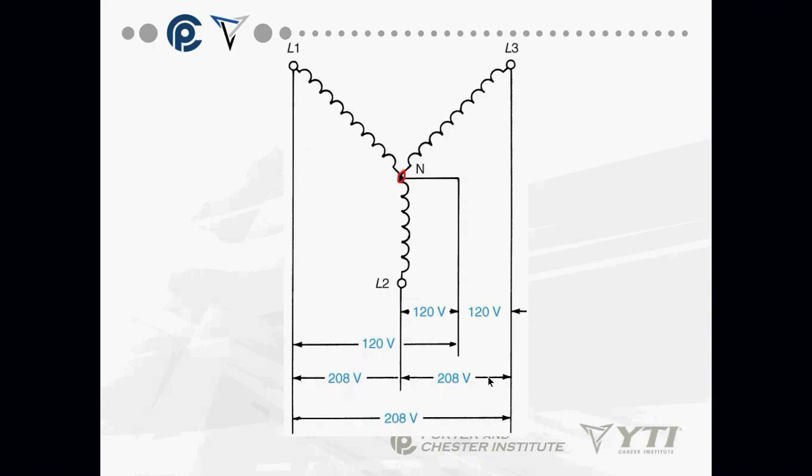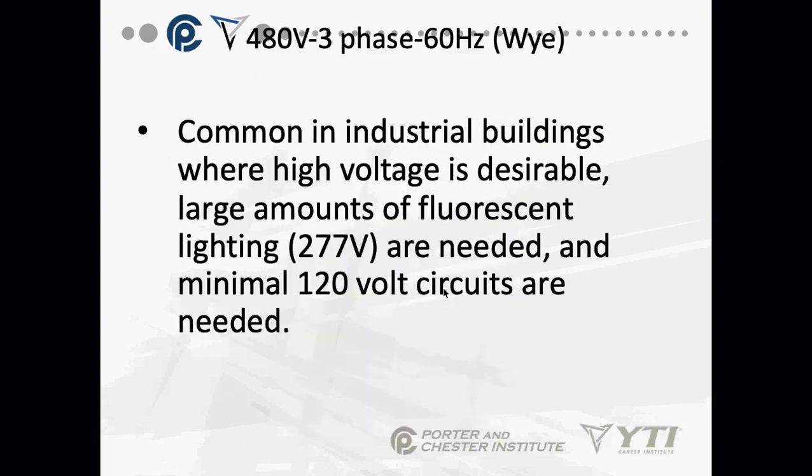I have my 208 volt here, but again, you can go up in power from 208 and you can get up into the 400s. That's my Y configuration, 208 volt. I also have 480 volt, three-phase, which is again on the Y configuration.